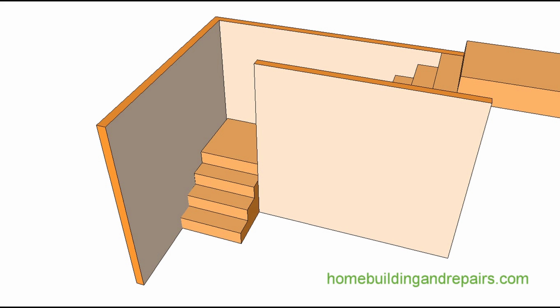I had my little tricks to maximize the step, like I said, adding a nosing to it, putting an undercut and a nosing, combining a variety of different tricks to get it to work more efficiently. But the bottom line is they're not as safe as the stairs built to the building codes today. They have been changed for good reasons.